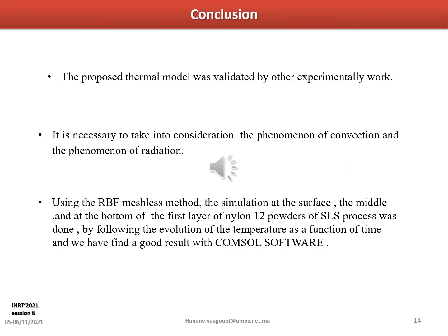In conclusion, the proposed thermal model was validated by other experimental work, and it is necessary to take into consideration the phenomenon of convection and the phenomenon of radiation. Using the radial basis function meshless method, simulation at the surface, the middle and also the bottom of the first layer of nylon 12 powder of the selective laser sintering process was done by following the evolution of temperature as a function of time, and we have found good results with COMSOL software also.